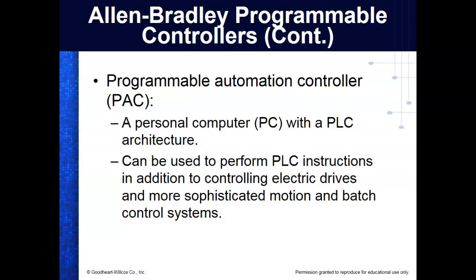So what we used to, and you can still run into these. Most computers now are programmed with a personal computer, even though there are some smaller ones that use a dedicated program. And how do we program them? We run an application that's developed by the company that sells the PLC. I couldn't use TIA Portal, which is Siemens, to program an Allen Bradley PLC. To program Allen Bradley PLCs, you have to use Allen Bradley's application. To program Siemens PLCs, you have to use the Siemens application.